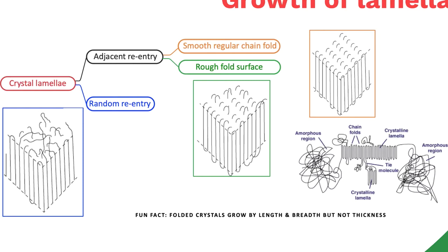Now, you remember one of the key parameters that impact melting temperature is chain length. The longer your chain length is, the lower your Tm is. And Tm is a direct reflection of the behavior of the largest crystallites at the highest possible temperature, right? And this is because long chain lengths cannot be packed nicely into a crystal lamella.